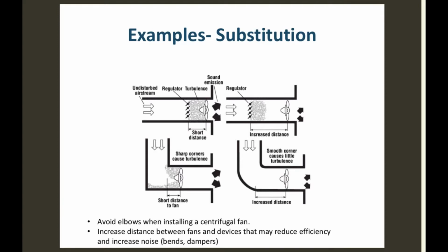Same thing with an industrial ventilation system. The velocity has to be high enough that you capture the contaminant and keep it suspended in the air so you can get it out of the building. So if you're dealing with a gas or vapor, right? Well, that's not going to fall out inside the ductwork, so you can have a nice slow flow through the ductwork. If you're dealing with fine dust, well, now the air's got to move a little faster. Otherwise, the dust's going to settle outside the exhaust duct, right?